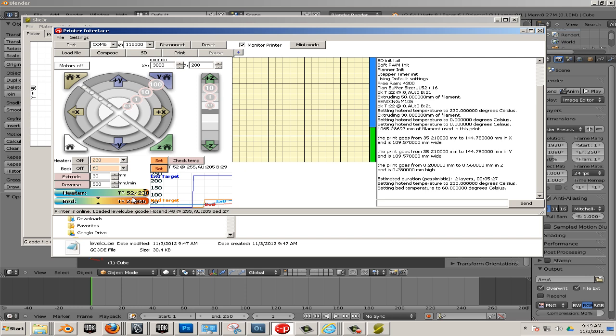So watch these numbers. They're very important. It shouldn't go over 230 degrees. If it does, it goes to 232, 235. That's fine. But it'll cap off at 240, and then it will shut off and go crashing back down if it gets to 240. Very rare that happens. And the bed, if you ever see that go past 85, in my humble opinion, don't let it do it. You can get it to 130 degrees Celsius, but it's so unneeded and such a wasteful thing of energy.